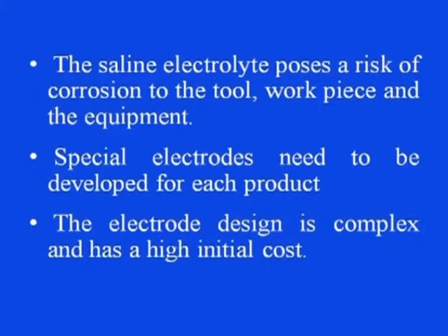Power consumption is more as compared to the other processes, because high current at low voltage is required in this process. The saline electrolyte used in this process poses a risk of corrosion to the tool, workpiece and the equipment. Therefore, this can be counterproductive in the long run.